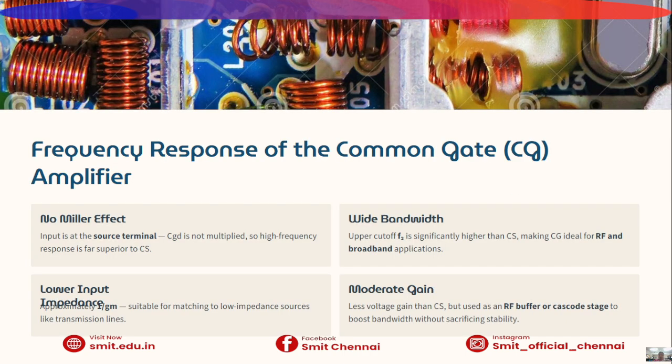Next, we see the frequency response of the common gate amplifier. The common gate amplifier offers better high frequency performance than the common source amplifier. One major advantage is the absence of the Miller effect. Since the input is applied at the source terminal, the gate-drain capacitance is not multiplied.